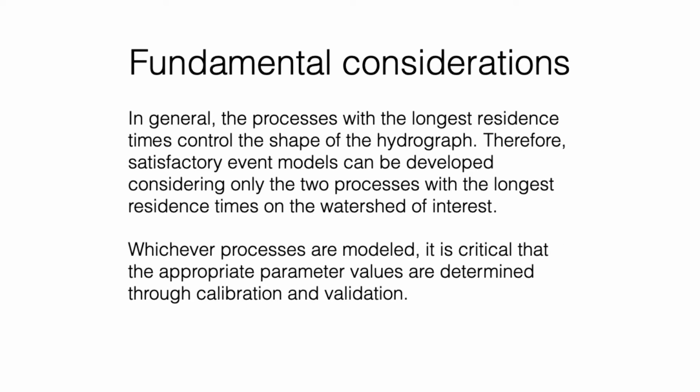After having decided a structure for the model, two procedures must be followed to determine the value of the parameters. The first procedure is calibration, in which the model parameters are changed and adapted to try to best reproduce the observed time series with the model. Once a best set of parameters has been determined, its overall quality is determined by validation, which is the process in which a new time series, different from the one used for calibration, is reproduced with the model, and the differences between the observed and the model time series are summarized by means of some statistic.